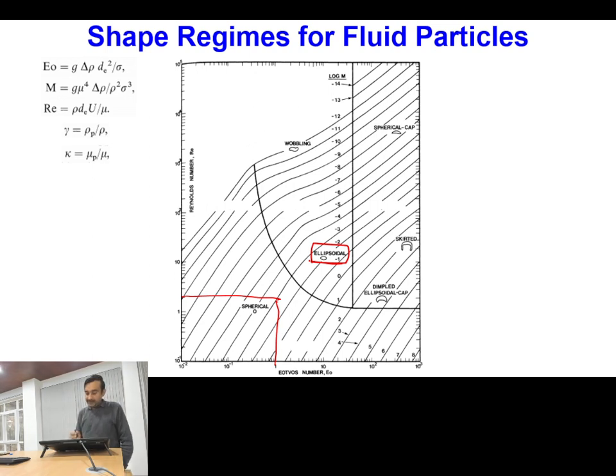Okay, and there is one more shape. If you go to very high volumes where velocities are sufficiently large, and the extent of the interface is large, different portions of the interface will be subjected to different types of forces. The chances of non-uniformity and instability augmentation at the interface will be more. Because of this, we will find that some interface waves are constantly traveling over the complete interface profile. This type of bubble shape is called a wobbling bubble. Is this one clear?